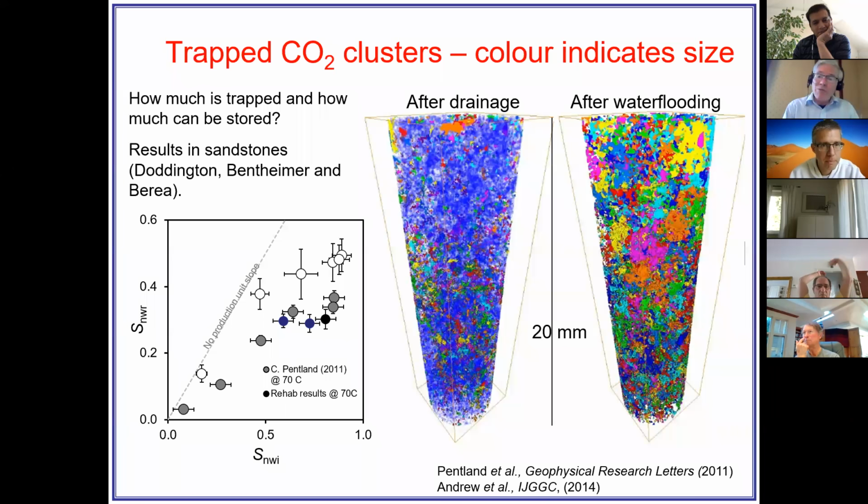Okay, we can relate it because we got classic water wet behavior. We got classic oil wet behavior that we can observe. And this mixed wet, which is interesting, where the contact angles are distributed around 90 degrees. But now we've looked at correlations. So we got our model. If we put the contact angle distribution and randomize it spatially and put it in our model, we get terrible predictions. So what we've observed is two things.